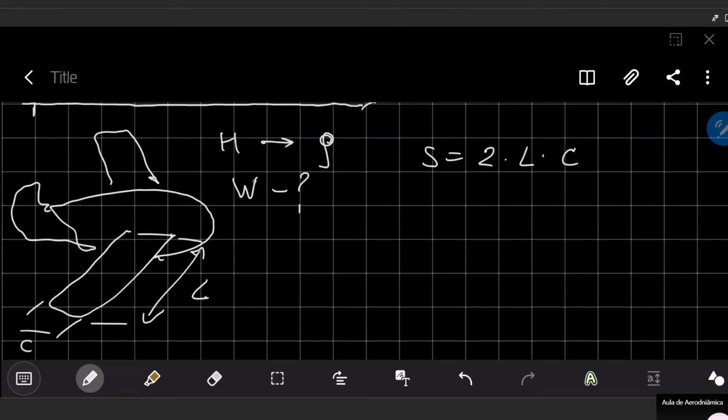You know the weight, you know the plane area. And then we start to play with the aerodynamic coefficients. We know, for example, the lift coefficient, which is lift divided by Q infinity S for our body. And L is the lift force, which is moving our airplane up.